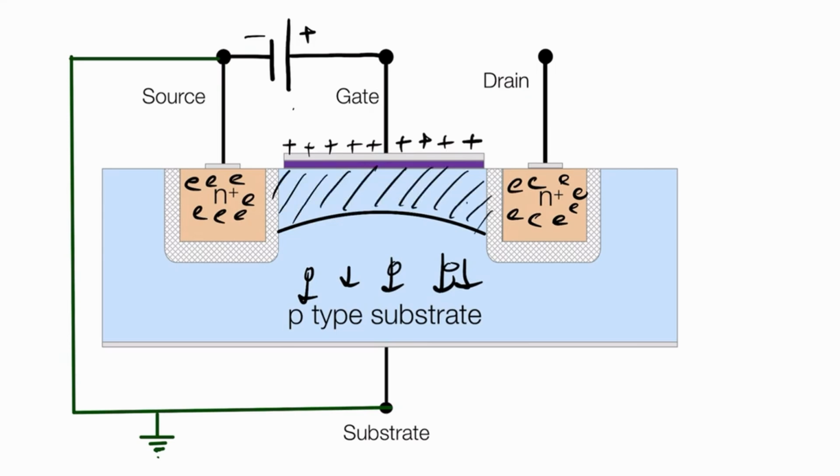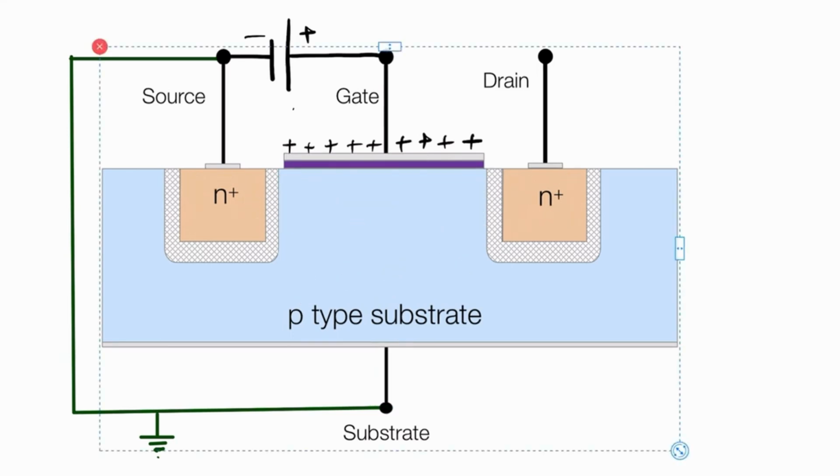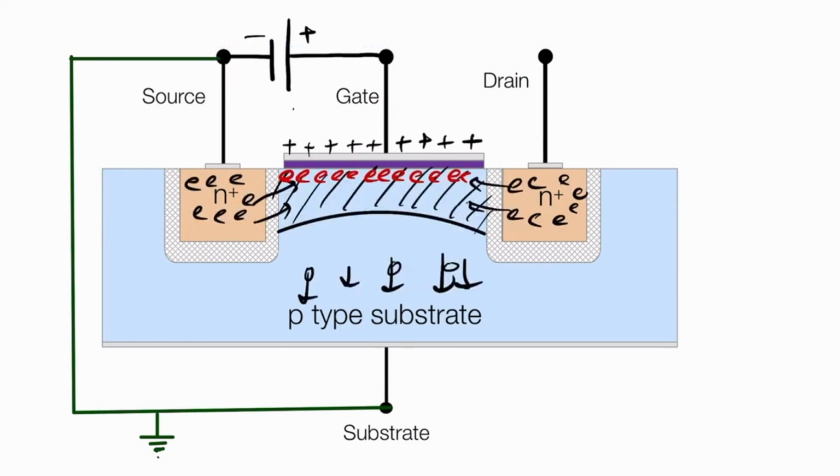At the same time, this positive charge will attract these electrons. So these electrons will move to this part. Here we can see the electrons will gather in this area. The electrons cannot flow to this part, as you can see this is SiO2, right? So they cannot flow to this part and go to the voltage source. Here we have the effect of the oxide. Okay. So as these electrons are gathered in this part, we can see here a thin N channel is created in this area.